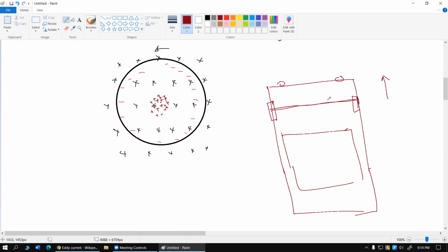To make eddy current introduced, we will have to have some metal disc somewhere attached over here, and around this metal disc we can have these coils introduced. And we can introduce the braking by conducting electricity through this magnetic coil, and that disc is going to heat up, absorbing kinetic energy from the whole car without any physical contact.